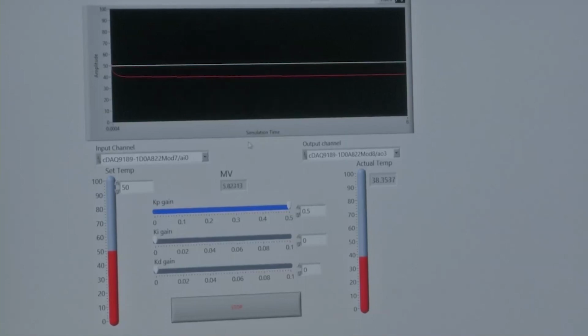Now the major problem with higher gains is, if you see the manipulated variable, whatever it is going to generate is 5.6 volts. So when 6 volts is applied as an input to the plant, it results in higher current, 6 amps of current. But you also have to see whether your plant can withstand pumping 6 amps of current or not. If that is the case, you cannot go with higher Kp gains too. That is another thing that you have to always remember.